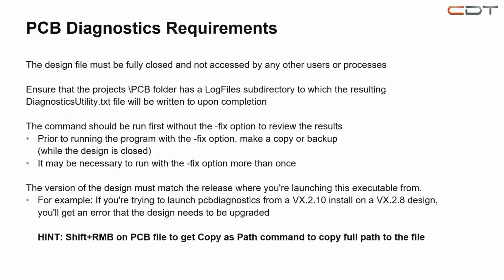There are some requirements though. As I said previously, the design file must be fully closed and not accessed by any other users or processes. And you need to be sure that the project's PCB folder has a log files subdirectory, because this check will create a diagnostics utility.txt file with all details.